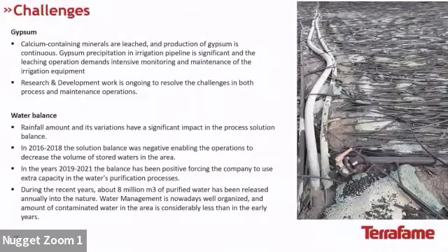As we all have our challenges, gypsum precipitation is the one for us. With the calcium bearing minerals leaching and sulfuric acid, we see gypsum precipitation in our pipeline quite heavily.